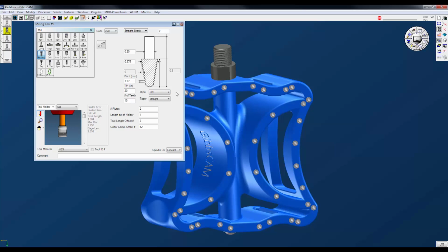When you define an angled thread mill, that automatically defines the angle of the tapped holes. And what I mean by that is you don't need to create angled geometry. If you have an angled thread mill, it will automatically create the corresponding angled thread that you need. So there's no addition of geometry or anything like that.